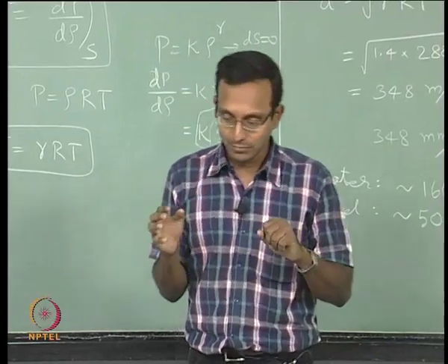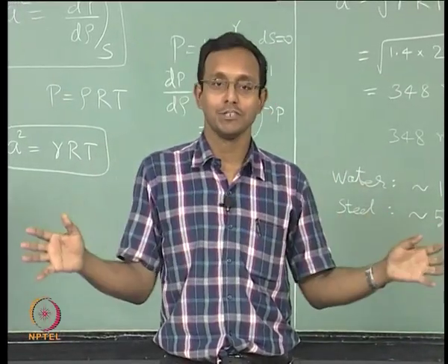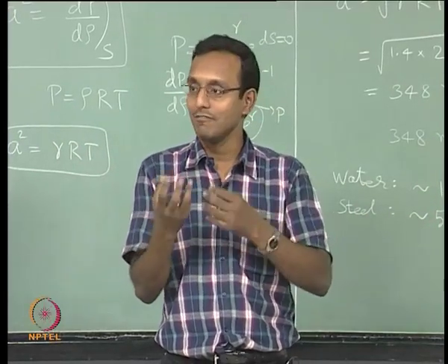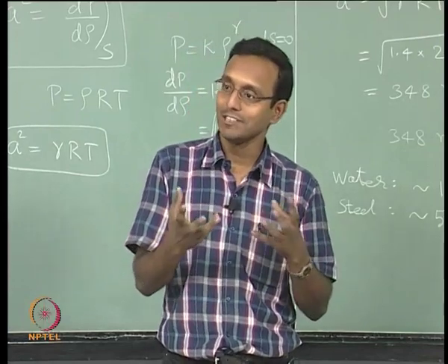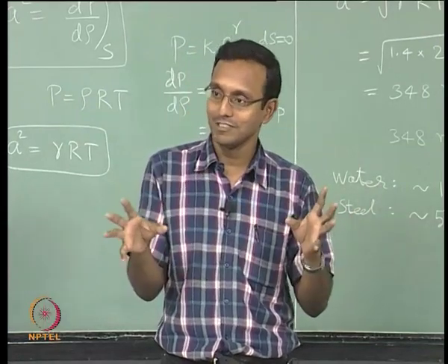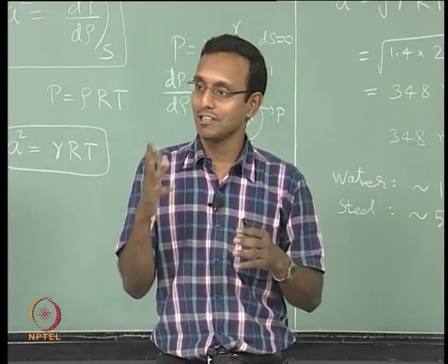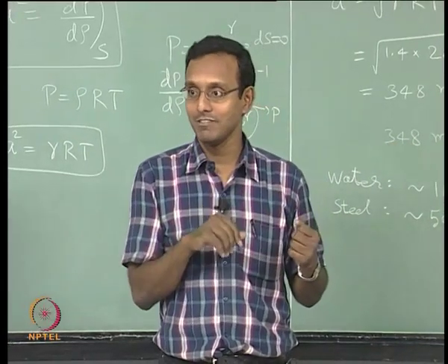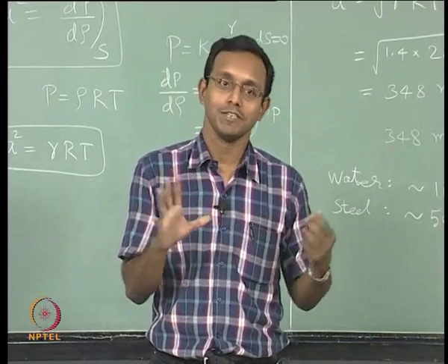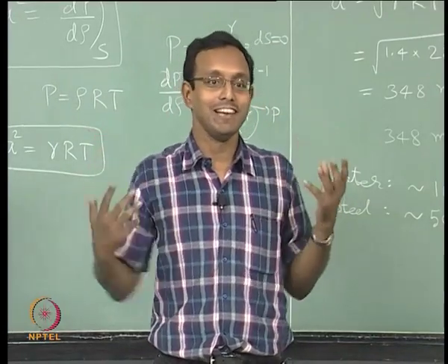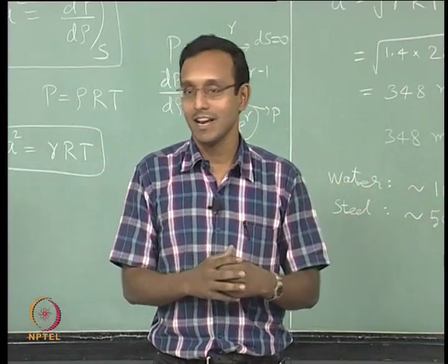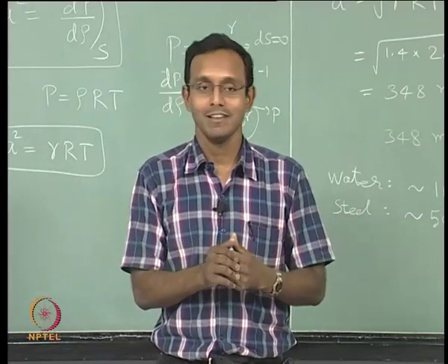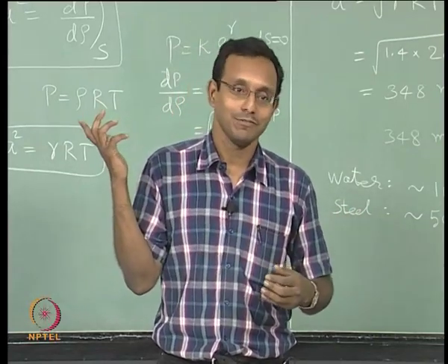Now if I think about any flow situation, if there is any change happening, then these kinds of waves will be generated. When the waves are generated, they are going to go through different processes. The wave could be a compression wave. If it is a compression wave, gas will move in the direction of wave propagation. If it is an expansion wave, it will go in the opposite direction of wave propagation. We got this idea from the physical field, from crowd dynamics, and I said that molecules do the exact same thing. You just believed me as of now. But we can even look at it from the equations point of view.